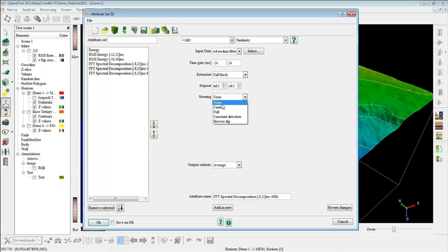I can create a different type of similarity, which is full steered, which is using structure oriented dip to compare the traces, or you can do it in a conventional way, which is a conventional coherency type. I will call it conventional similarity, which is non-steered, which is not using structural dip, and I provide its time gate 24.